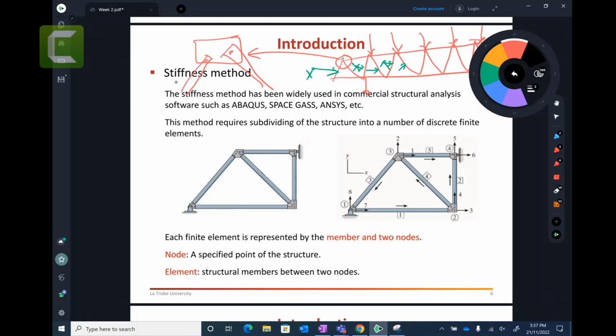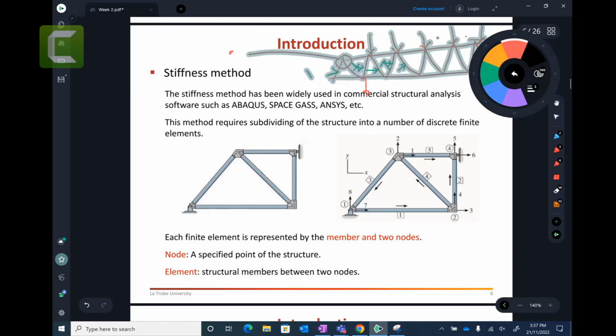If I apply the load here, the moments or the bending will not transfer from one member to another member. I hope you can understand. If you have welding, like if I weld directly on this one and rotate this one, they will rotate. But this is a plate, and that plate separates them, so they are in separate zones. If one member bends, the other members will not bend. So that's the truss. I hope you understand this one.